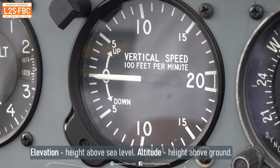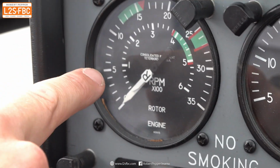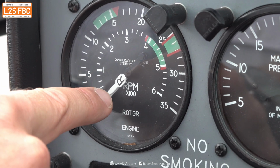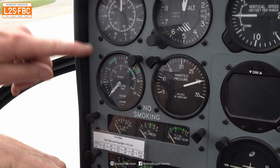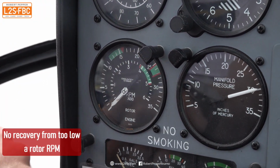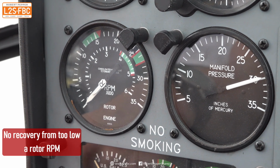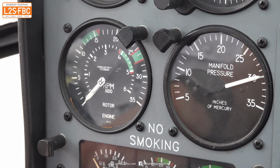Out here, the next row down on the left, we've got the tachometer. It gives us information about the outer scale, the engine RPM, and on the inner scale, probably most important for a helicopter pilot, the rotor RPM, and I'm talking about the main rotor. The engine, yes, we have to look after the engine. It's very important, as all of you know, but the rotor RPM is what keeps us alive. If that gets below the red line over here, it's over for us. So whatever we do, once we're off the ground, we have to keep that in the green at all times.